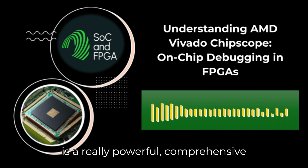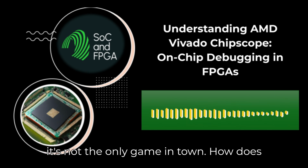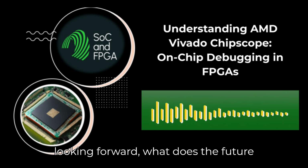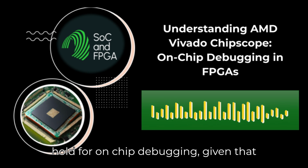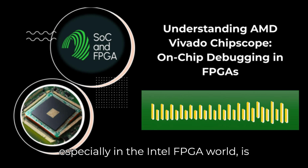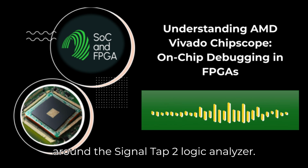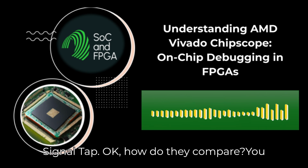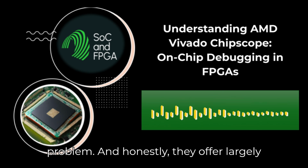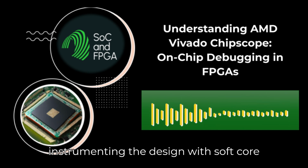It's clear Chipscope is a really powerful, comprehensive solution from AMD Xilinx, but it's not the only game in town. How does it stack up against the competition? And looking forward, what does the future hold for on-chip debugging, given that hardware just keeps getting more complex? That's right. The primary alternative, especially in the Intel FPGA world, is their on-chip debug solution, centered around the Signal Tap 2 logic analyzer. Signal Tap? Okay. How do they compare? At the core functionality level, they're aiming to solve the exact same problem, and honestly, they offer largely equivalent capabilities. Both involve instrumenting the design with soft-core analyzers.